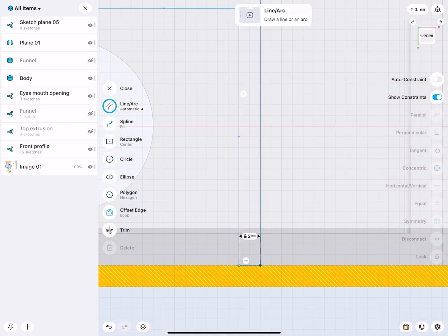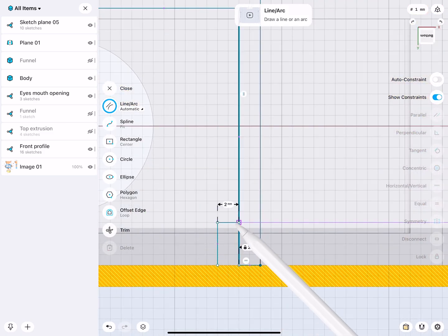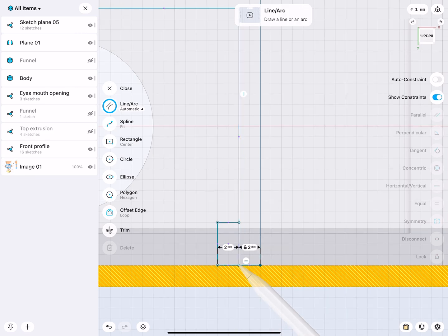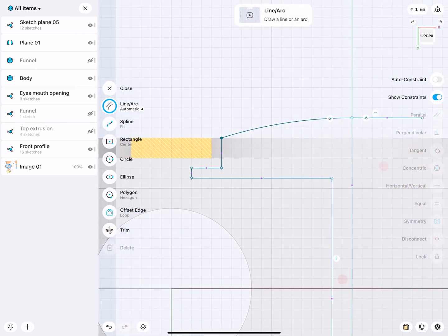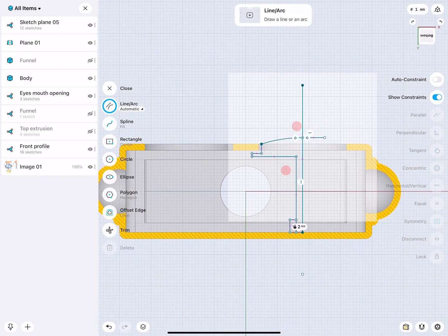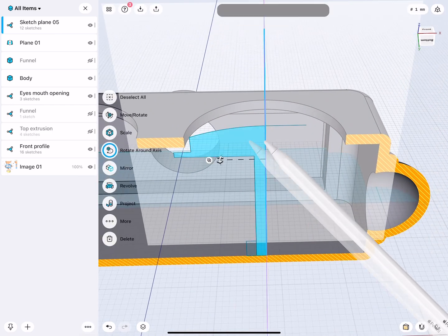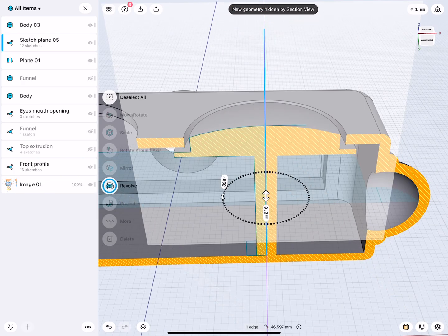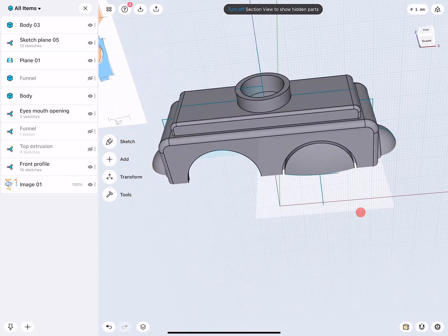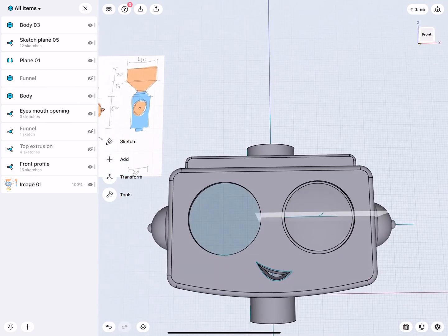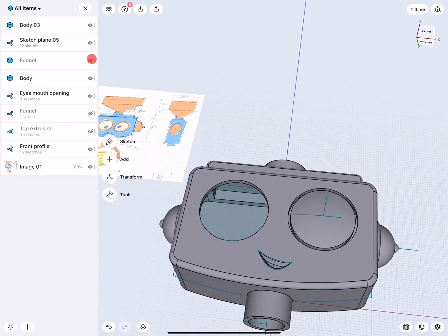This layer at one point has to sit in some sort of a socket. So here's, for example, the socket. This one here has this element, so the eye doesn't pop out. And it's rotated. There, you see how easy this is. This construction plane also we don't need anymore because we always have the sketch to go back to it.